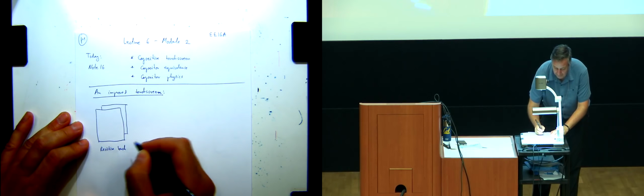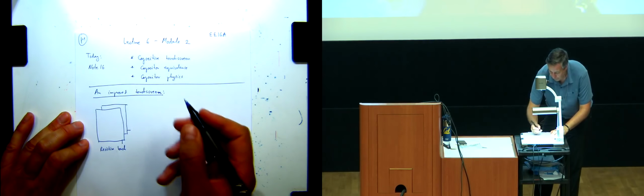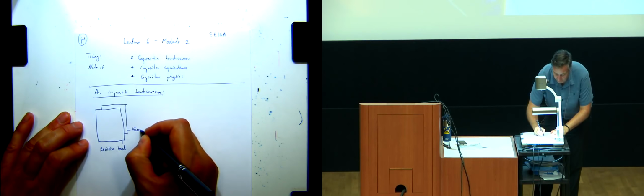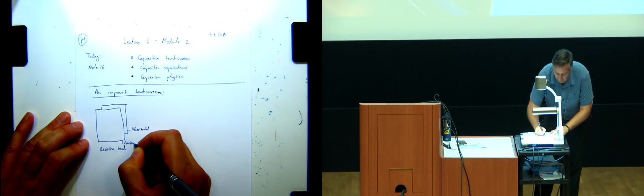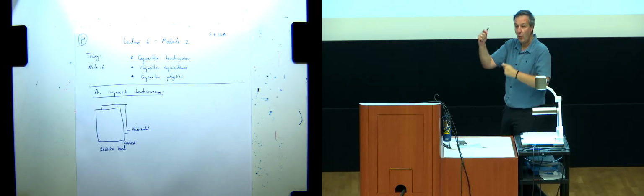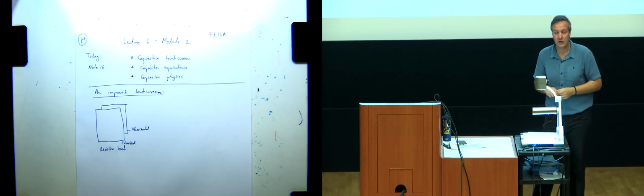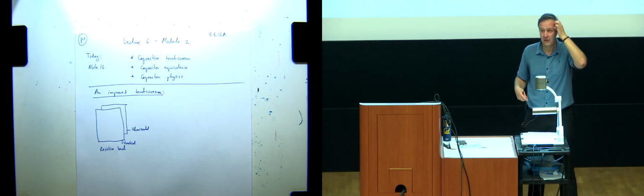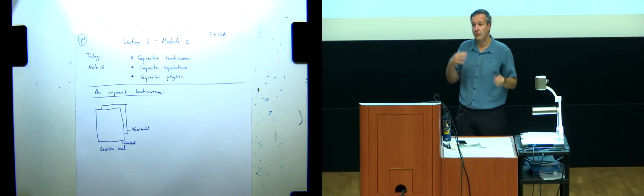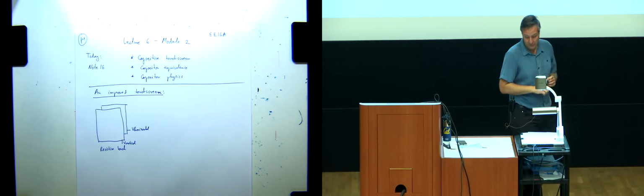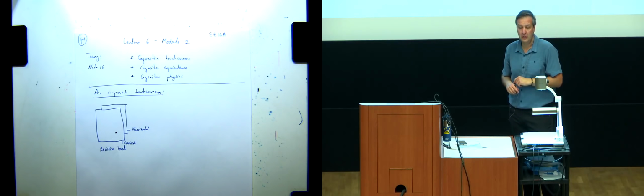Two planes, and we said that if we alternate them, we will be able to find out the horizontal and the vertical position by just changing where we measure while we apply the voltage to the opposite conductor. We derived the whole set of things through voltage dividers that showed us that we can indeed measure the vertical first and then horizontal position of the finger. And that was the case if you pressed in any given location on the touch.